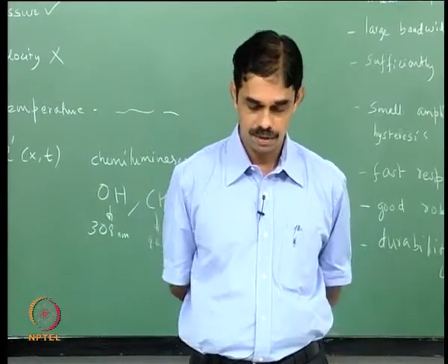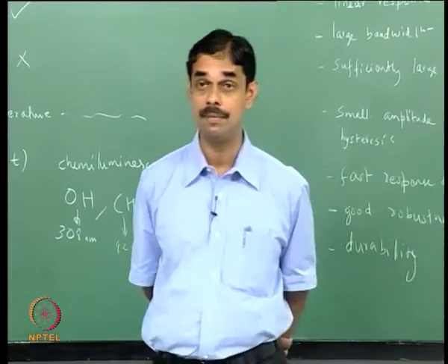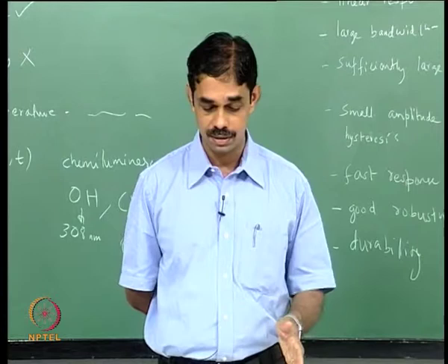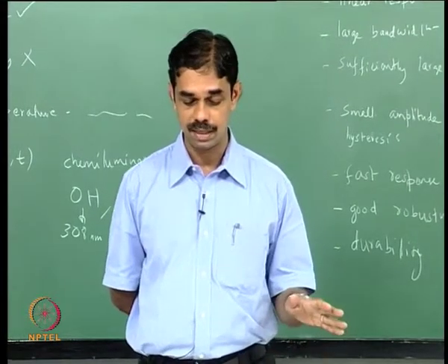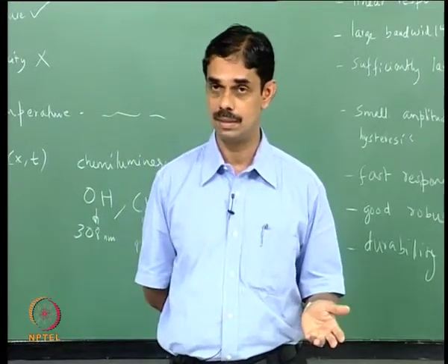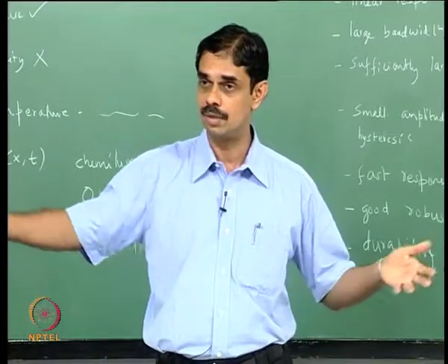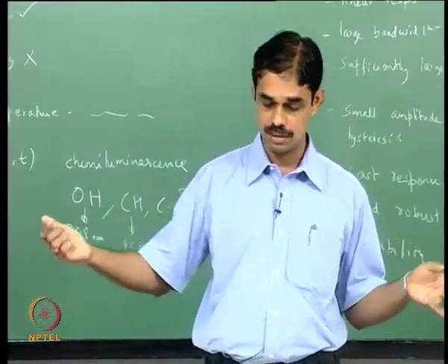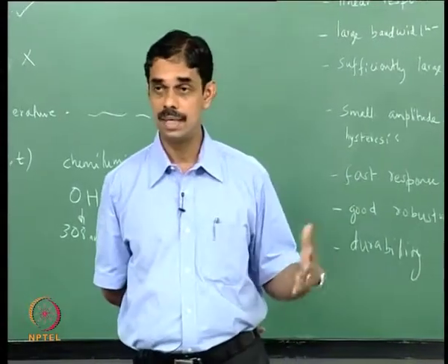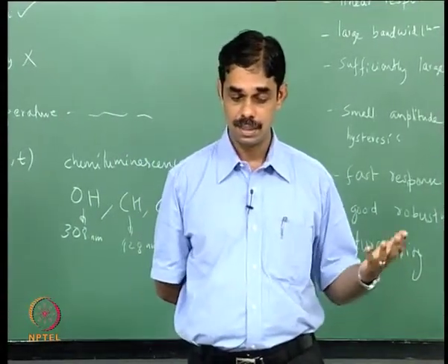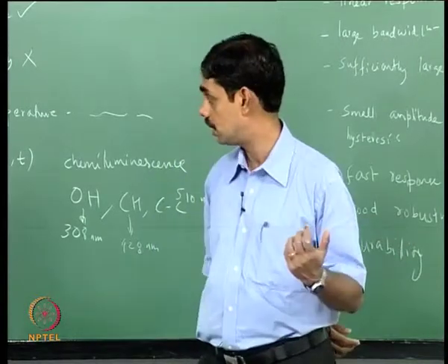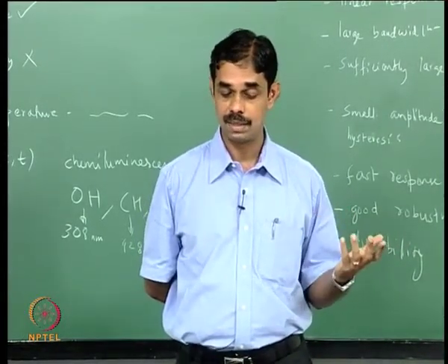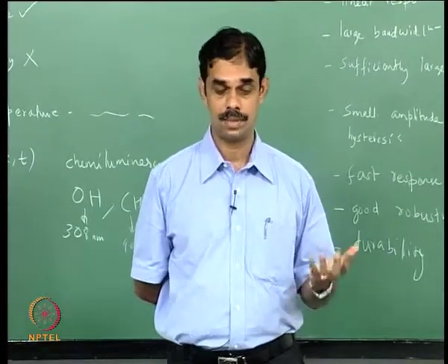The big advantage of online system identification over offline system identification is that the controller keeps track of changes in the combustion system dynamics due to varying operating conditions. For example, the mean temperature may be slowly rising, or the fuel composition may change slowly and so on. So if there are changes in the parameters, then the online identification procedure can identify adaptively and respond to these changes in the operation of the combustor.